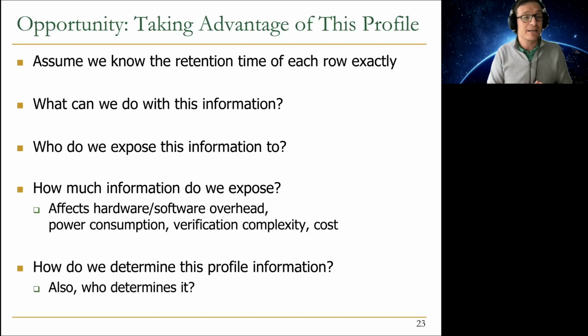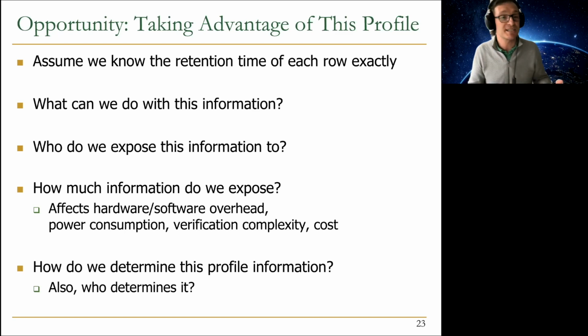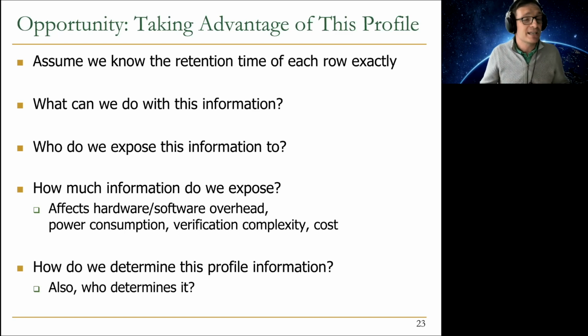But later, let's say 1 day later, you test this DRAM cell and you check how long it retains data. It may retain data for only 16 milliseconds. So this is a problem called the variable retention time problem. And I like thinking of it as a quantum-like effect in modern circuitry. It's not predictable. This process is random. And randomly, a cell's retention time changes.